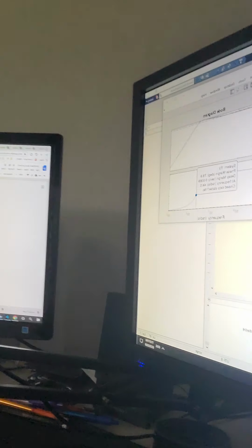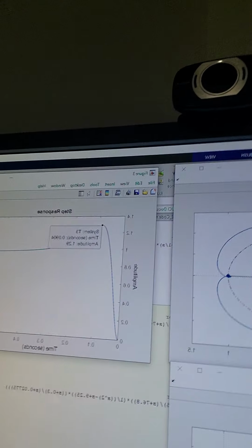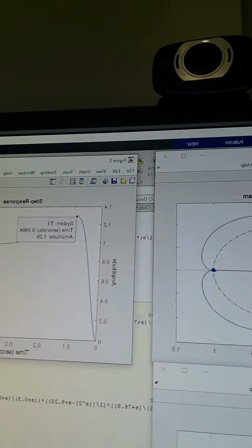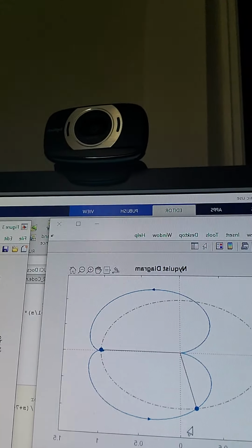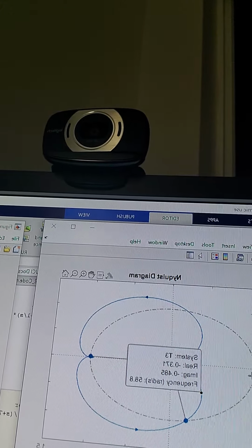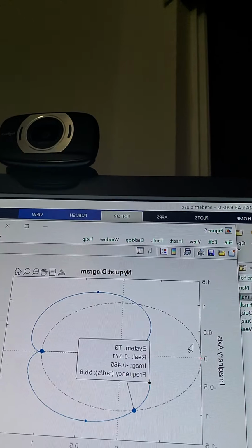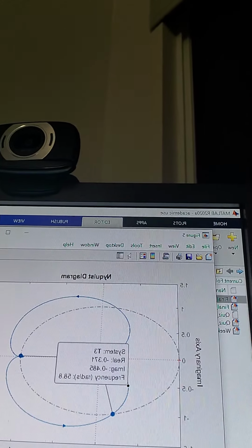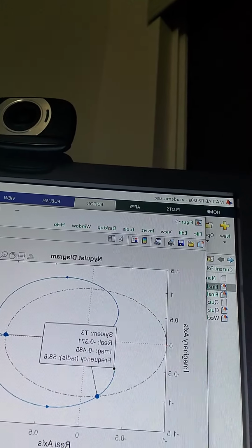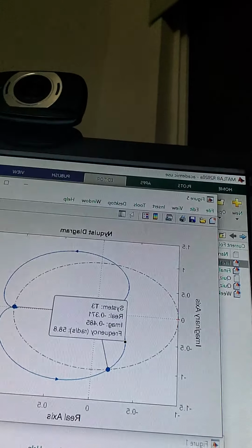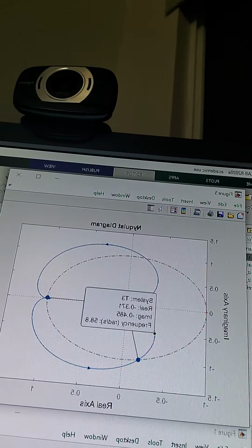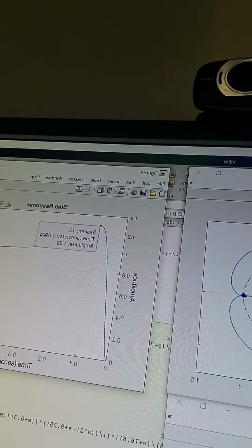And then I did attempt to do a little bit of manual tuning on the compensators, but as you can see from the Nyquist diagram, we're actually pretty close here, from this edge to 0. We are actually right around about 0.9. So unfortunately, the system is very sensitive. The smallest tuning can cause it to spiral out of control, which is why I was not able to get this thing to actually be stable.